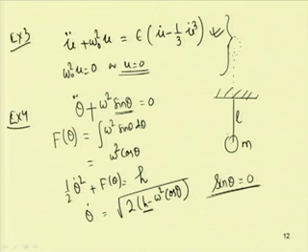When we carry out the stability analysis of the system, we can see that one equilibrium position is a stable equilibrium position, while the other is an unstable equilibrium position. In the absence of damping, the stable one represents a center and the motion will be periodic, but the other equilibrium position will be an unstable saddle point. So, one can plot theta dot versus theta to qualitatively analyze the flow or trajectory of the system.